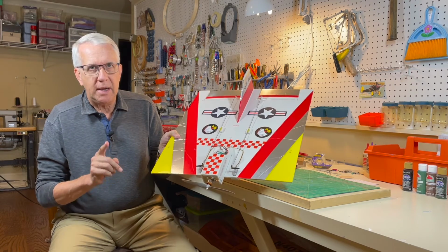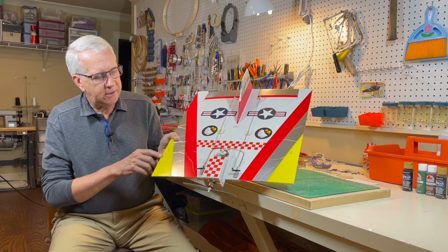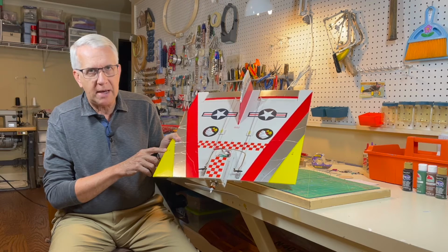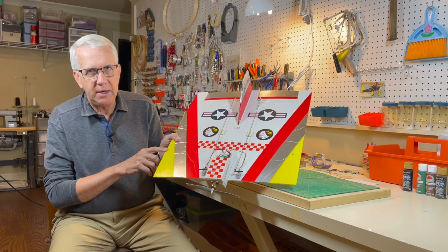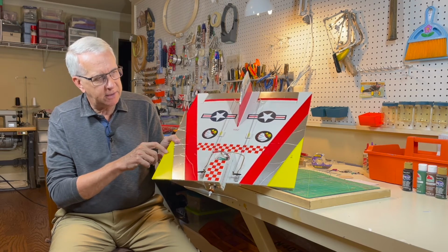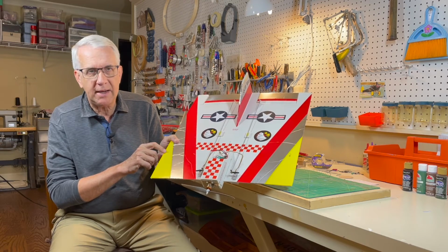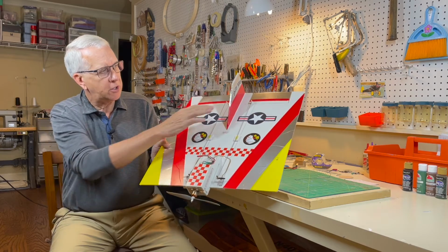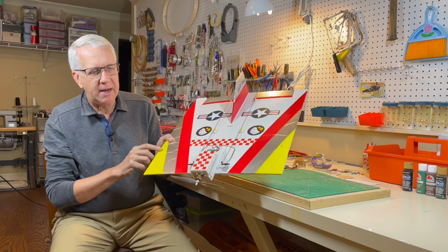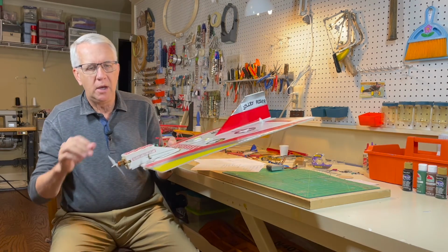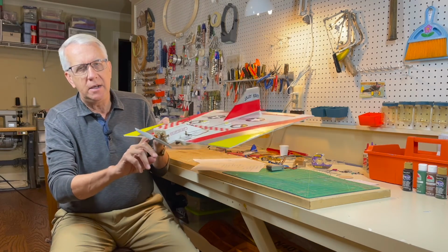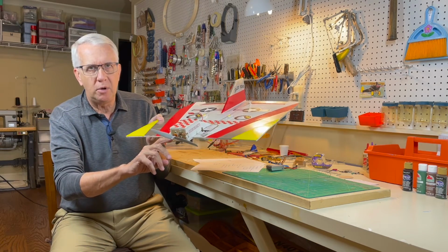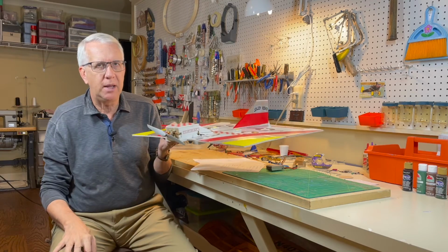So on this plane, I did locate the center of gravity. It's just 25% of the way back, 1/4 or 5 inches back from the leading edge, and I marked the center of gravity. That's where the plane has to balance. The problem is there was enough structure in the back of the airplane that when I reached this balance point, it was a little bit tail heavy. So what I had to do was to add some weight into the nose bolts to keep it balanced out with the battery in place.